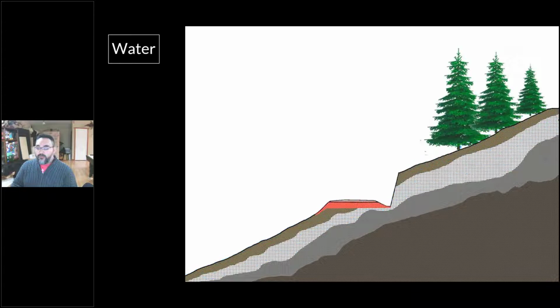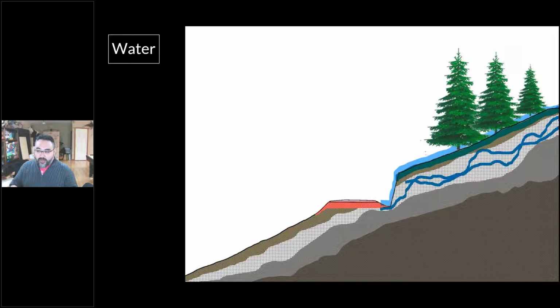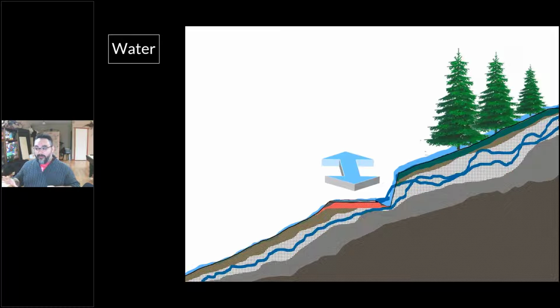So now we've intercepted that water. We're accumulating it because it's changing its velocity, and then we can redirect it up and down or across the hill slope as it flows down the road or flows in the ditch. So the important thing to remember, as I said at the start, is that these things will always happen no matter what you do when you're building a road.